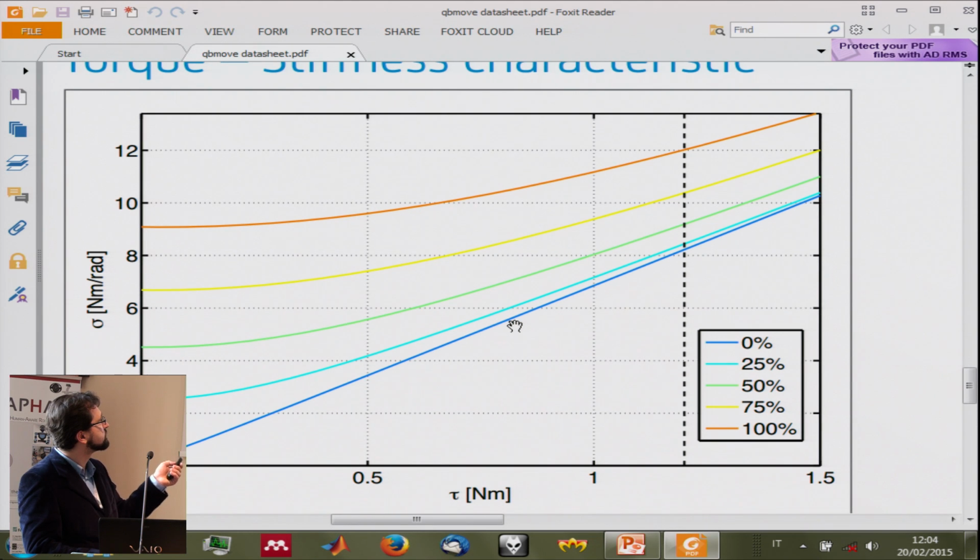And what is constant on this line is the internal stiffness preset, which is defined as the difference of position between the two motors. So this percentage is on the stiffness range at no load, and then starting from that configuration, we keep it constant and we increase it.